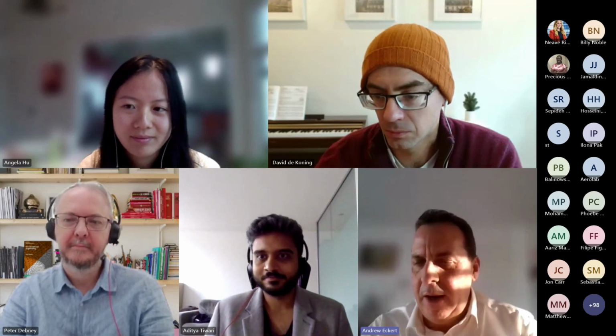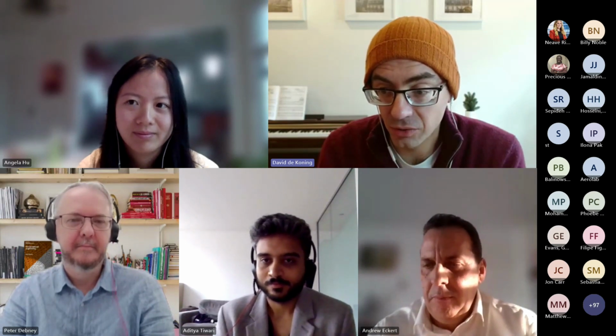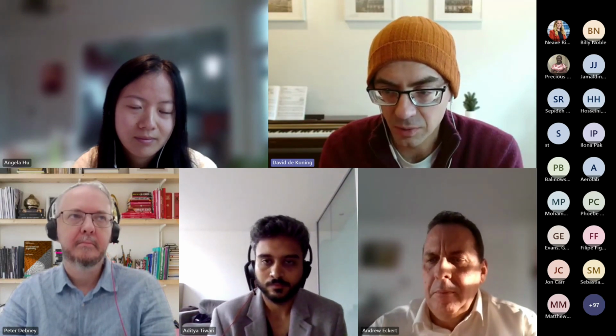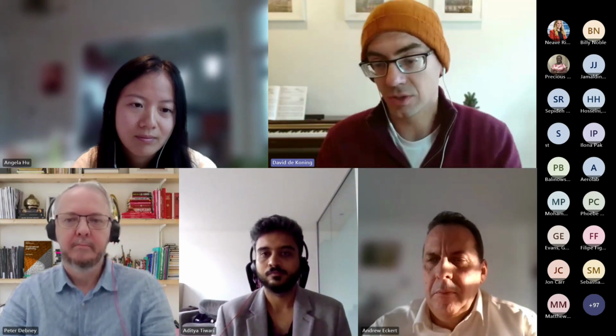Right, so next question is, how do I use GSA with Grasshopper? And David, I'll hand it over to you. Yeah, so I won't go into detail right now, but I did drop a link into the chat to the tutorials. We have a set of tutorials and then a set of deeper how-tos on the doc site. It's all very simple. If you have GSA installed, you can go to the Rhino package manager and search for GSA and click install, and you are off to the races. It doesn't get installed with GSA, but with the GSA license, that includes being able to use the Grasshopper plugin. So it's not an additional purchase. It's part of GSA.